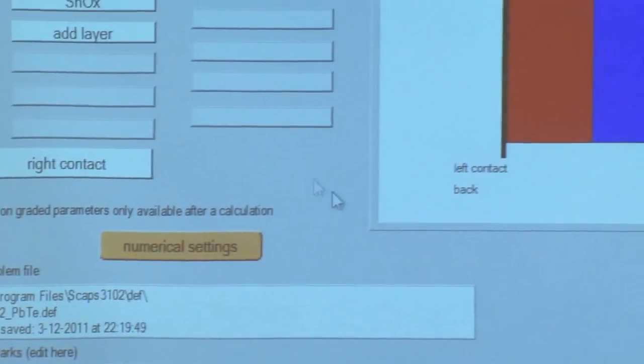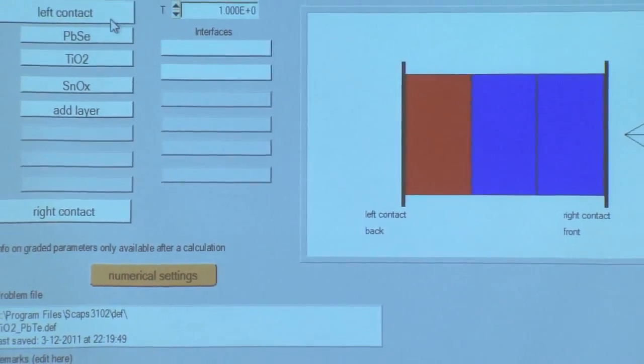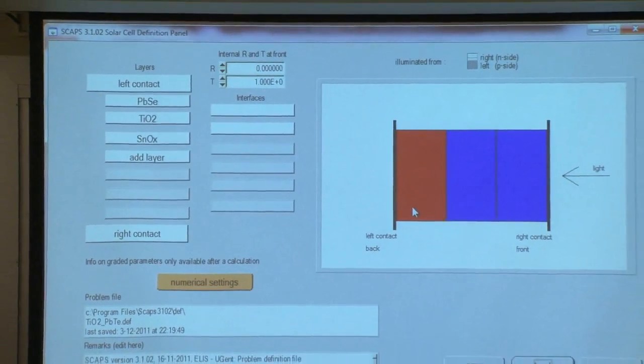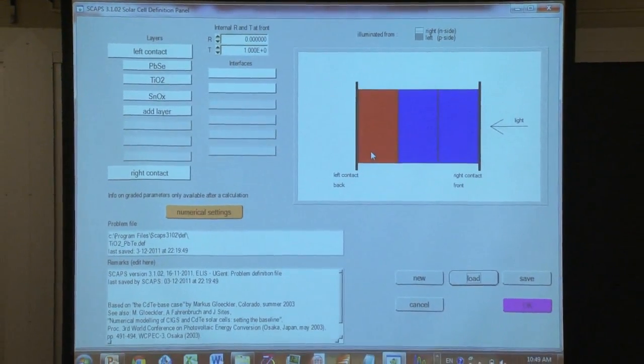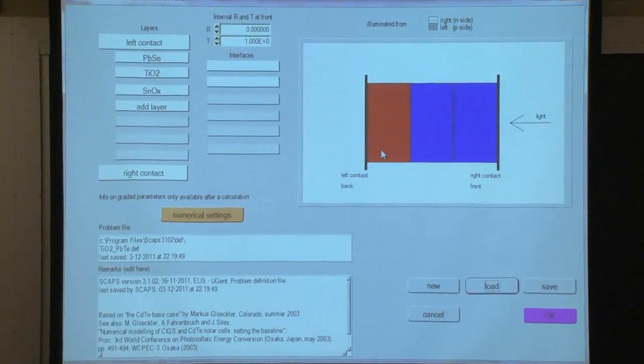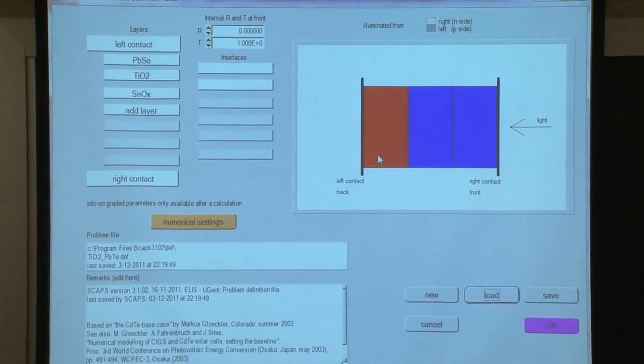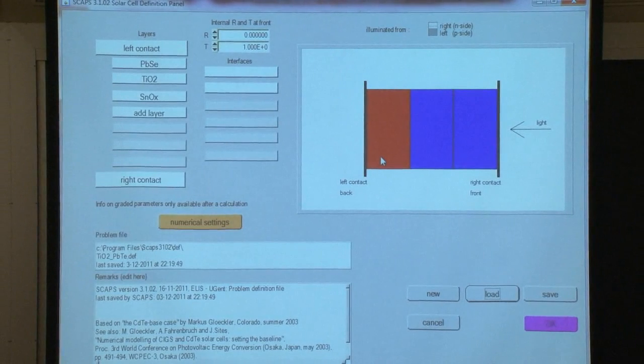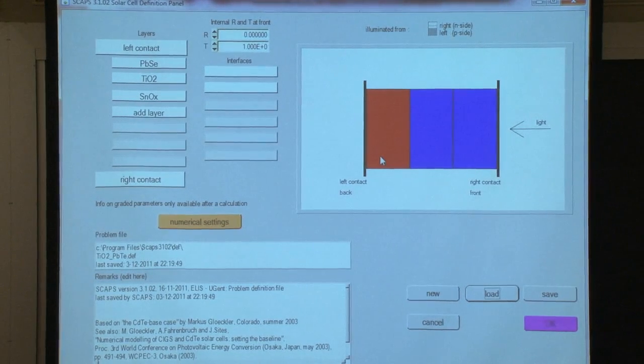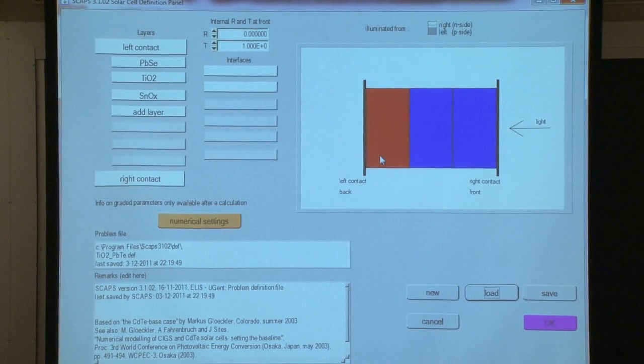If we want to do the bulk heterojunction, we could just put one layer with effective material properties. However, the hard thing was that we should set the band gap in the parameters, and we could not define the band gap because even if it is just one layer, it is a mix of 2 different materials. So it's hard to define the band gap, and it will mess up everything. So we couldn't.